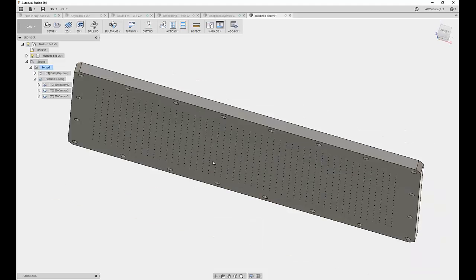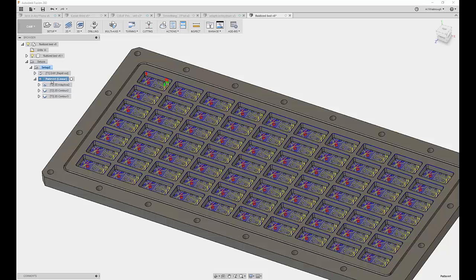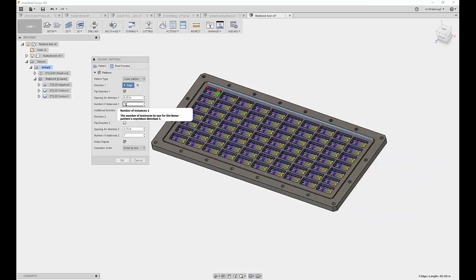So in this case, I've used a pattern to create all those toolpaths. This is something that happens very, very fast because it's just a translation. There's no toolpath calculation happening whatsoever. I can say I want 15 instead of 10, and it calculates very fast because there's no toolpath calculation whatsoever. So sometimes we like to overuse the computer. I was thinking the analogy last night.